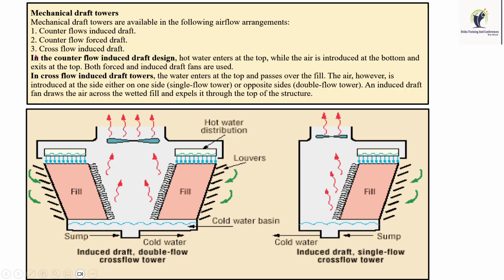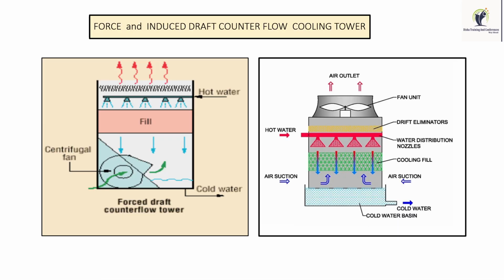In the counter flow design, hot water enters at the top while air is introduced at the bottom and exits at the top. Both forced and induced draft fans can be installed. In cross flow, only an induced draft fan is possible, with no forced draft fan.